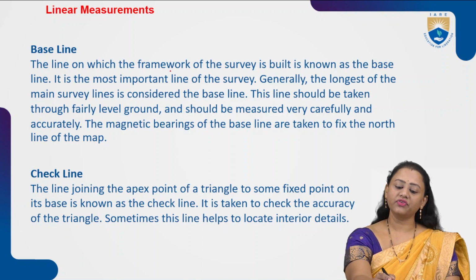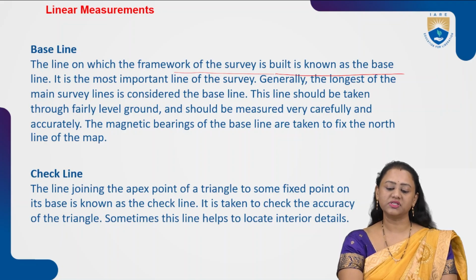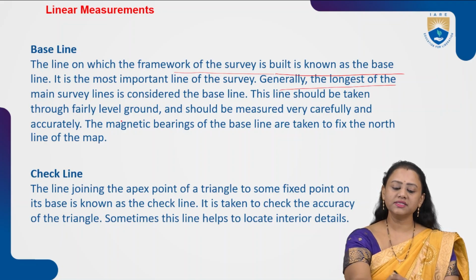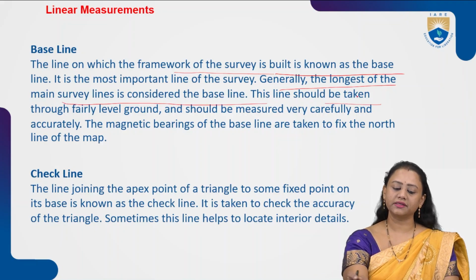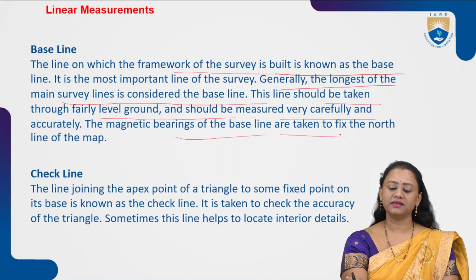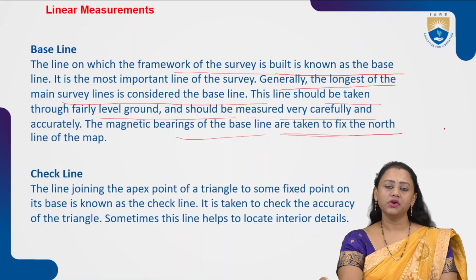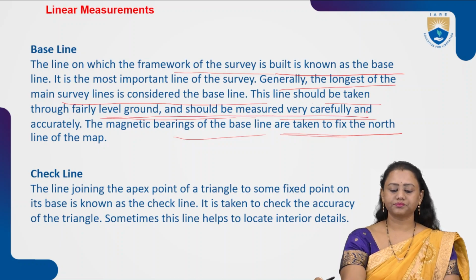So the line on which the framework of the survey is built is known as the baseline. It is the most important line of the survey. Generally, the longest main survey line is considered as the baseline. This line should be taken through fairly level ground and should be measured very carefully. The magnetic bearings of the baseline are taken to fix the north line of the map. So, a baseline is the main line upon which all other measurements are taken.